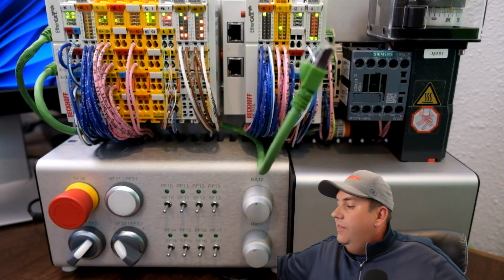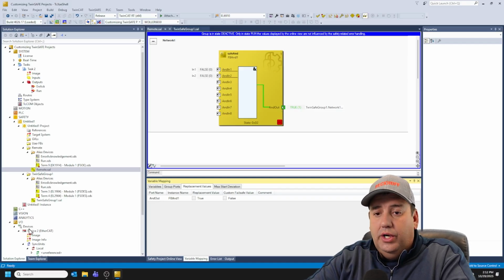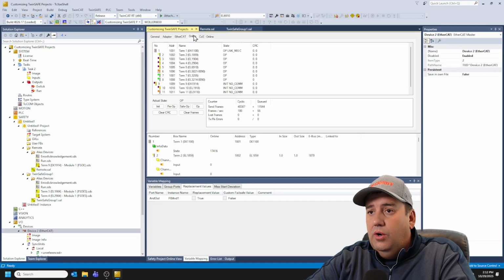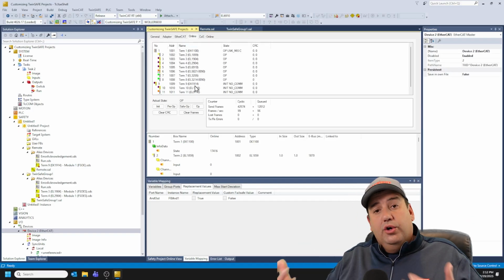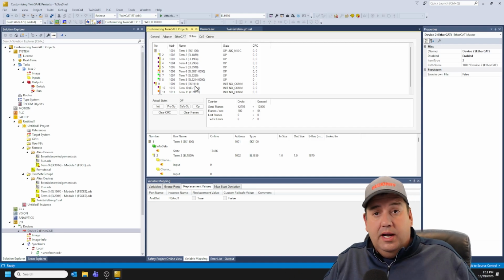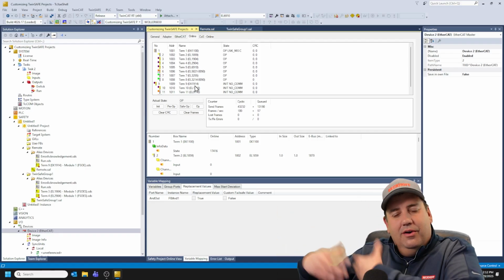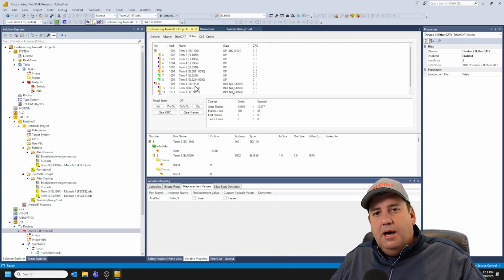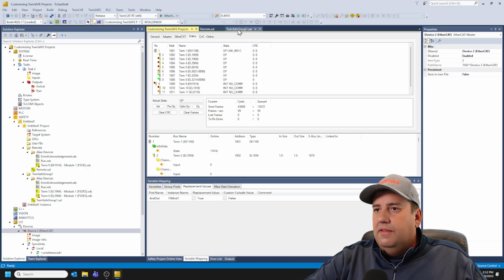So we're going to disconnect this, and we didn't break anything because we're in separate sync units. If we go and look at what's going on in device 2 online, we can see we're in op, but we say, hey, there's a link missing because our EK1914 just dropped out. It's not there. Now we're going to want to do other things in our programming other than just the safety to actually not have this hardware there and make sure that the rest of our project is operating. But hopefully you can see what we're getting from the safety side.